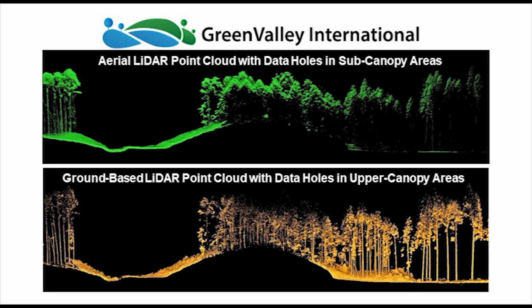Now, for those of you out there who don't quite know what I mean when I say data holes, they are regions of a point cloud where no 3D data exists. They occur where an object or surface with a mappable spatial structure can be found. However, this surface was occluded from the surveying instrument's field of view during data collection. Information gaps of this type can present troublesome or debilitating quality issues during the development of project deliverables or the running of operations that make use of laser scan data.